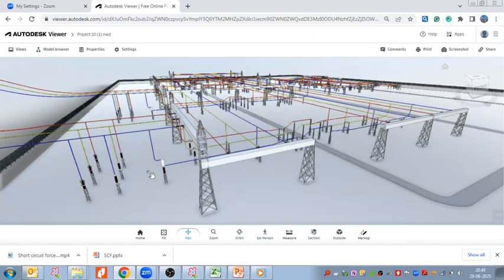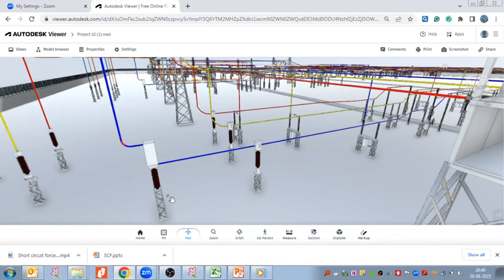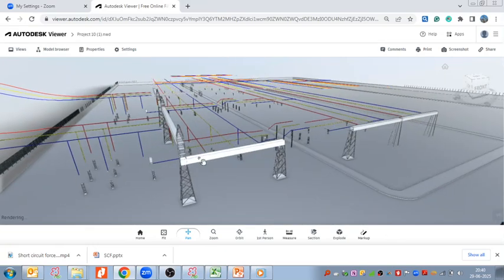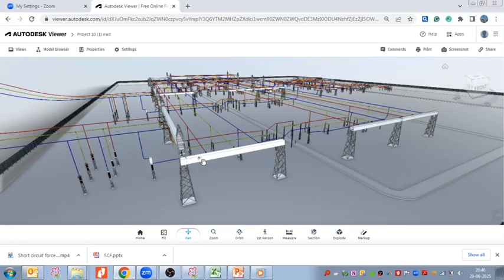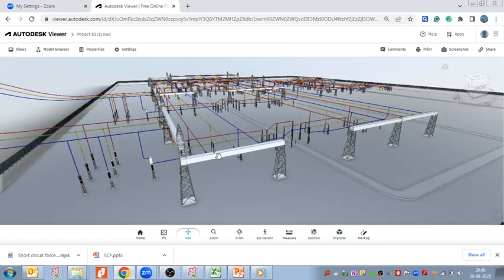At the same time, when we are doing the equipment installations, we are installing on the support structure. So this support structure, the tower and gantry, is designed by the structural design engineer in case we are doing any utility project except the power grid, because in the power grid, PGCIL provides their standard drawing for all the equipment support structures, towers and gantry.